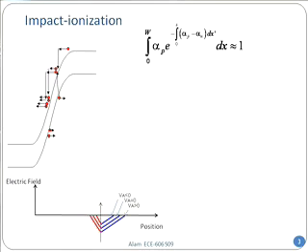If you want, you can put the right values in and you can do the integral. But if I set alpha_n and alpha_p equal to each other, then what should be the fate of the exponential? Well, that will be gone because that's e to the power 0. Now that's getting simple enough. Further, I'm going to assume that alpha doesn't really depend on position. Because if the electric field is constant from 0 to W, if it's so constant, then I can say alpha is a constant.